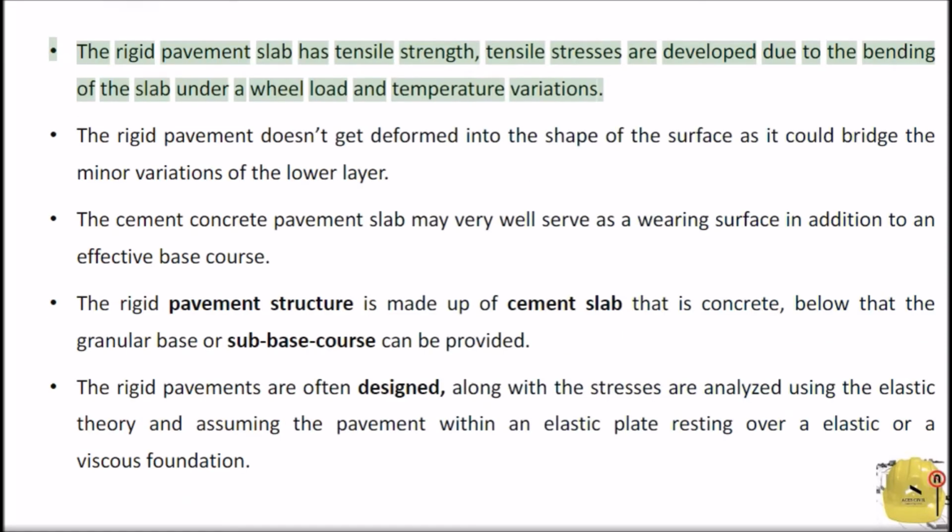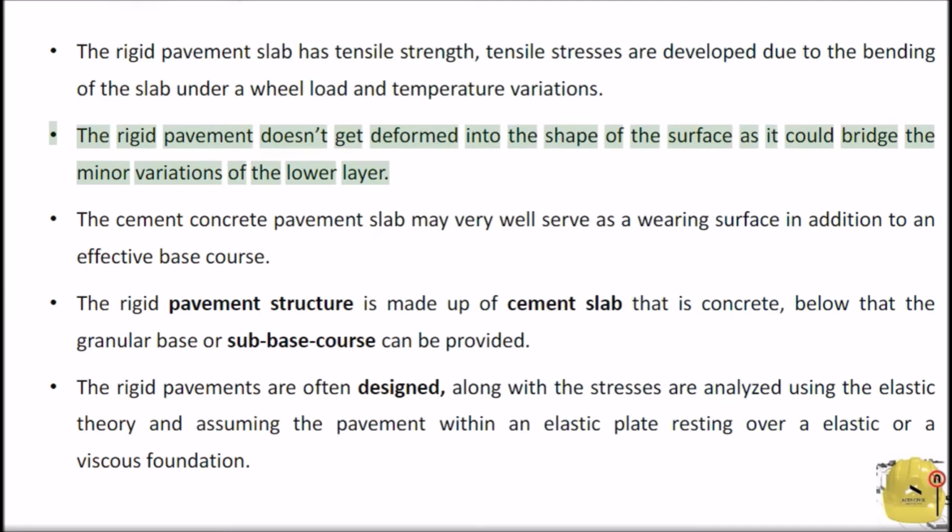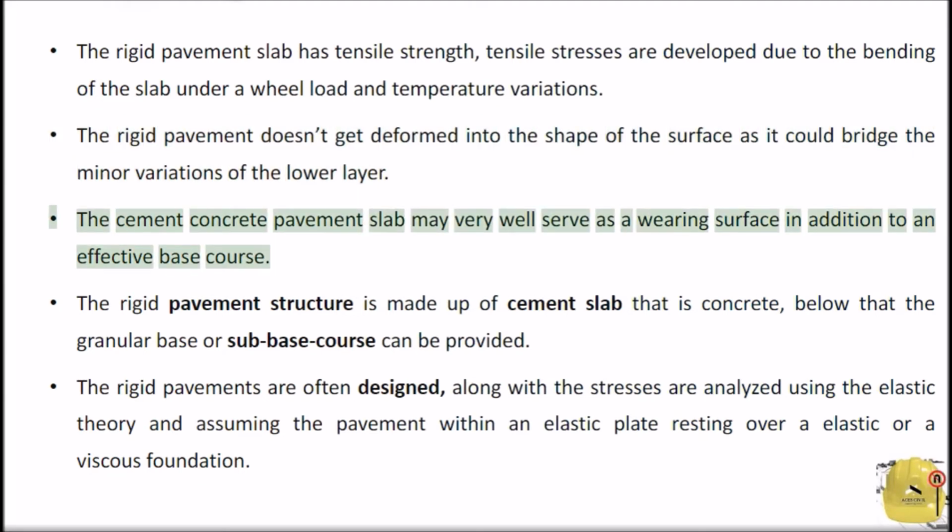The rigid pavement slab has tensile strength. Tensile stresses are developed due to the bending of the slab under a wheel load and temperature variations. The rigid pavement doesn't get deformed into the shape of the surface as it could bridge the minor variations of the lower layer. The cement-concrete pavement slab may very well serve as a wearing surface in addition to an effective base course.